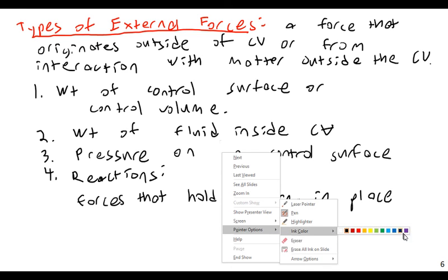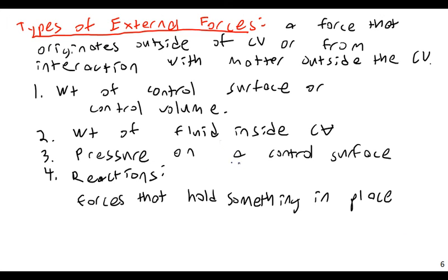And then, further note, for this pressure here, we never use absolute pressure. This is always gauge. Unless you want to do a big integral across the entire surface of the external pressure, I suggest you don't do that. I mean, you can do it in absolute pressure, but you're going to have to do a surface integral across the outside of the control volume of all the pressure from atmospheric pressure, et cetera. So I advise not doing that.